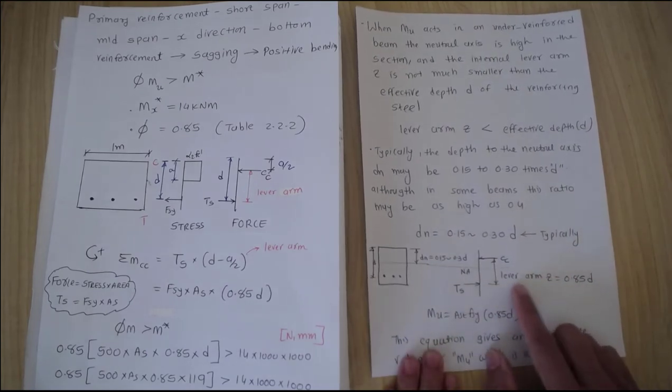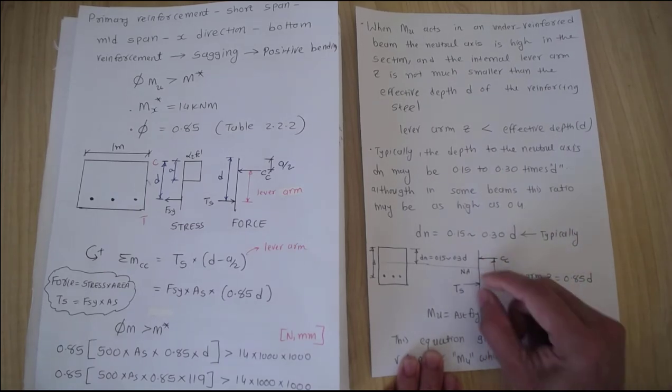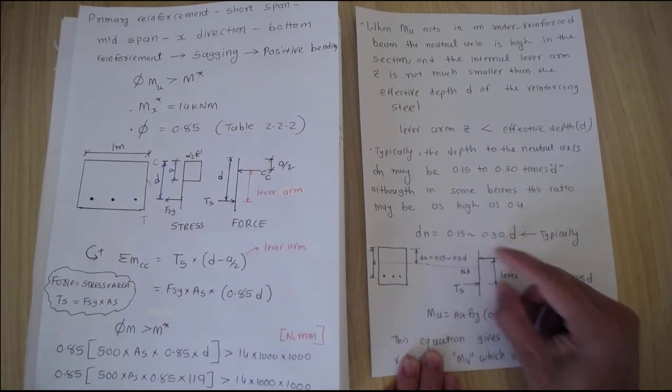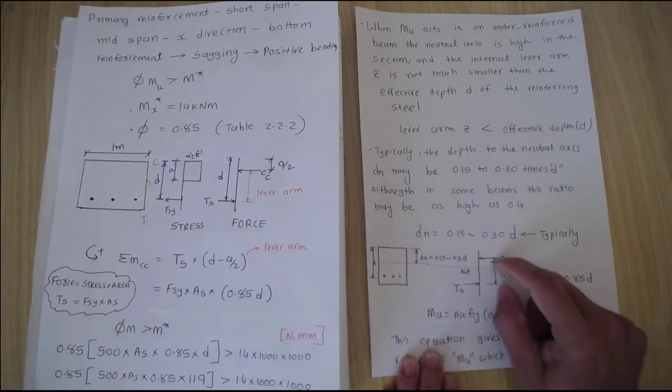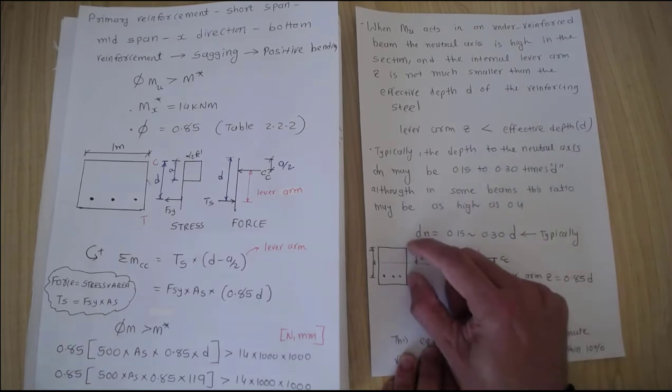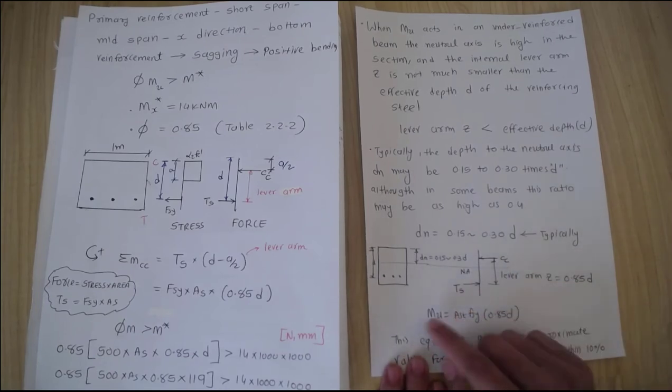So in that case, if you want a lever arm Z, typically we take it as 0.85 d. As I mentioned, we don't want to take too small a lever arm, we want a reasonable one. So if you have a d of 100 millimeters, this lever arm would be 85 millimeters. That's what I'm talking about. I don't want to make it a 10 millimeter lever arm. I'm taking 100 because it is mathematically easy to explain. Otherwise we would have real numbers.